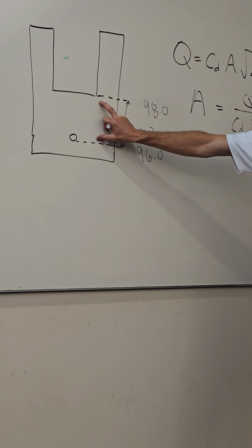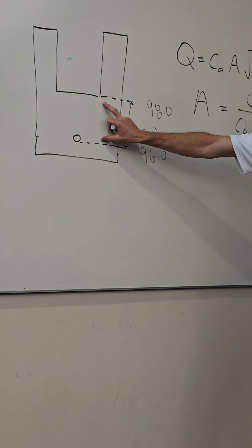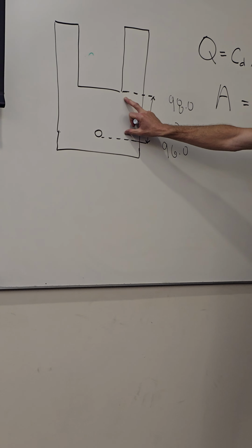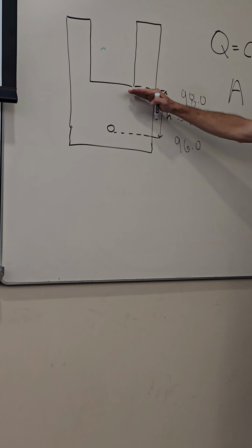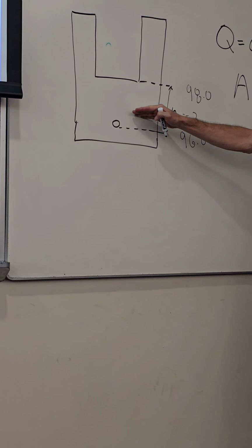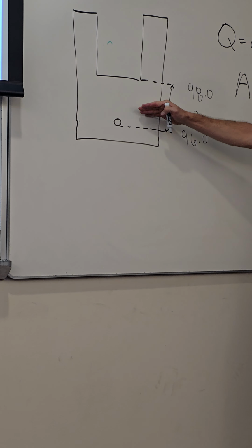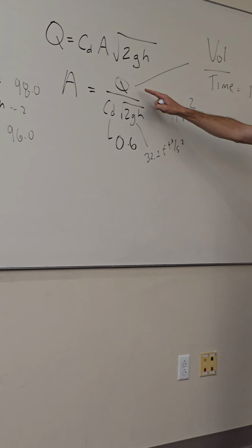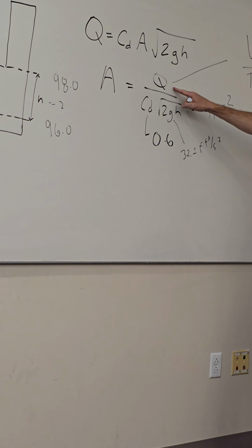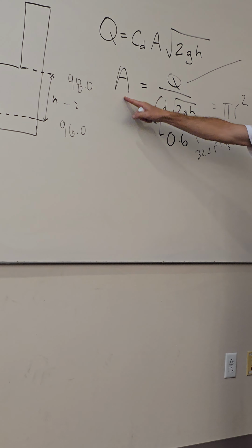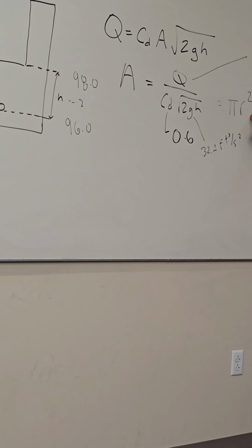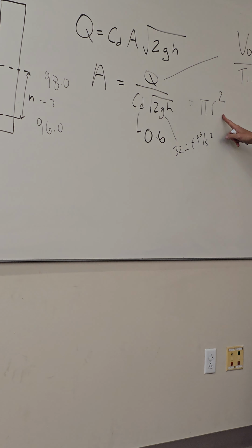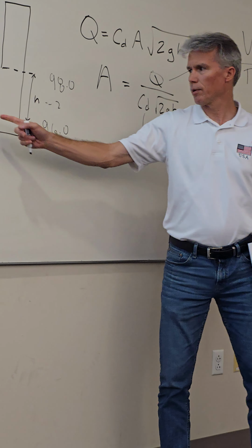Anybody? Yes. You do, right? Because you have a stage, area, storage relationship for your pond. So I can calculate this volume, right? You agree with that? So if I know that volume, I know my time, I know flow. So if I solve this for A, I can come up with a radius, okay? And then that would define the size of the radius.